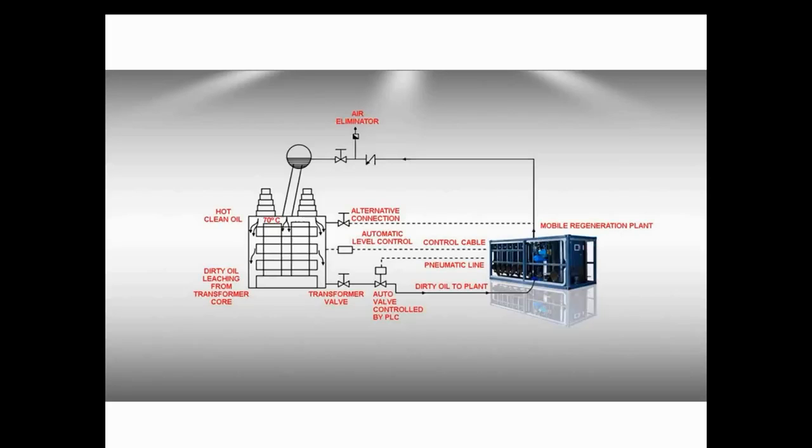One more problem regeneration escapes is mixing oils. Usually, all older oils of different brands, such as Nynas or Shell, can mix with each other, except Chinese oils. There was an experience some years ago when, after regeneration, a couple of different Chinese oil brands mixed. After 1 year, the oils reacted with each other and got black. When Nynas says that its oils can be mixed with others, most probably this company aims to protect the oil market, but we can't completely eliminate the risk.